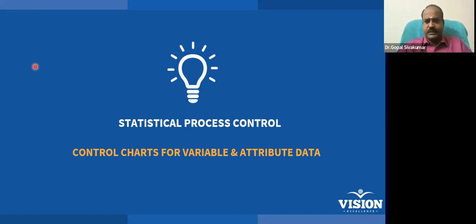This is the primary reason we require a tool called control chart. A control chart can let you understand whether your process is under control or not. If it is under control, we conclude that the process is stable. If the process is stable, you can proceed and check its capability. If the capability is not up to the mark, you can move on to the next step, which is called process improvement.